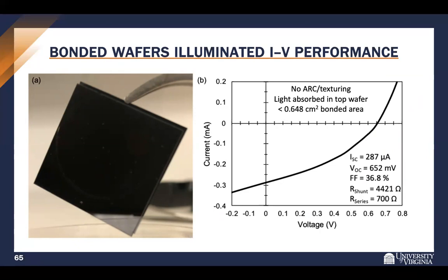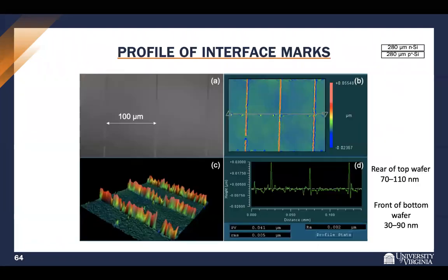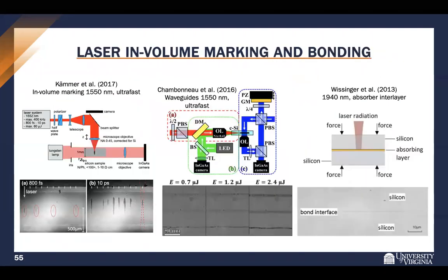So if people use, let's say, nonlinear optics with a femtosecond laser system, the 2-photon absorption or some sort of photon mixing, so you get really localized heating, do they get much better bonding and performance if they did all of that? I've never seen bonding with 2-photon absorption. At least I wasn't able to find anything on that. Most people have just created cavities or waveguides or things for microfluidics. The only person who did the bonding used an absorbing layer and a 940 nanometer laser, which I believe was also picosecond. This 940 nanometer wavelength is super transparent to silicon, so he's not relying on any 2-photon process. But yeah, the ultrafast laser system would be quite expensive. Yeah, I think if your approach is successful, that probably would be a lot more. It could work. We just don't have the tool. That would be fun to explore.